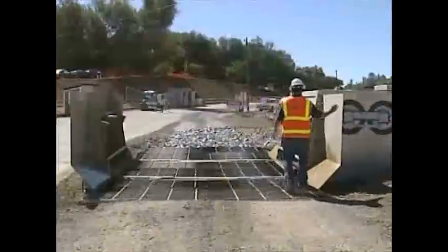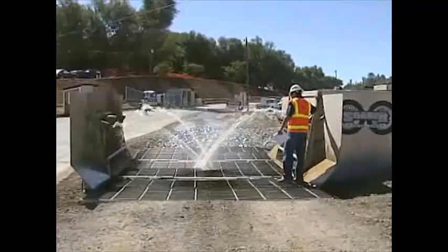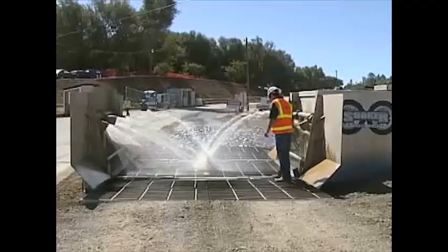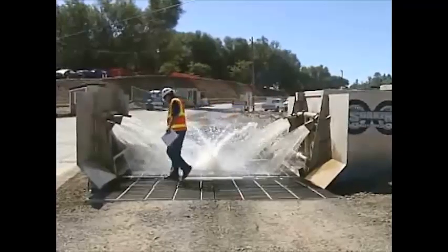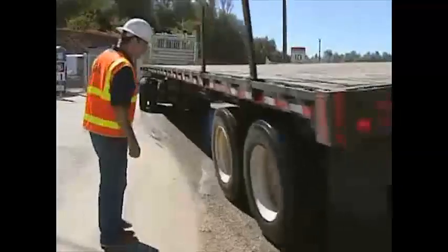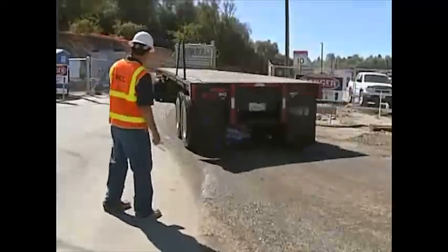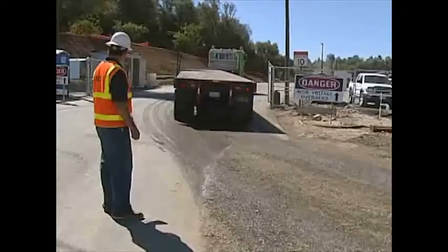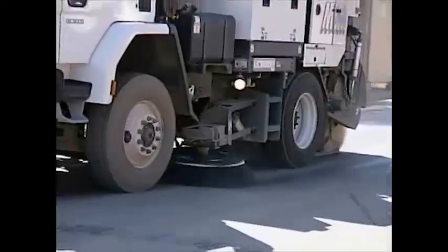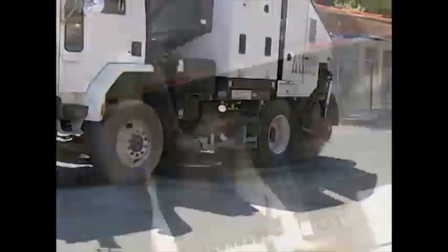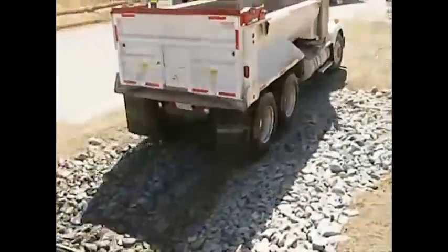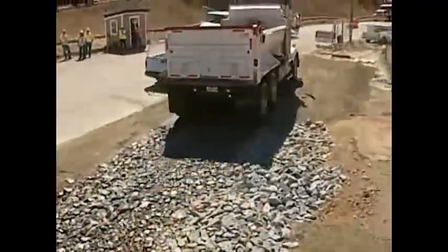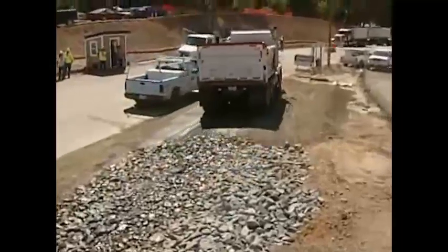Check for proper function of the tire wash as well as any form of damage to its components. If damage is detected, repair it as necessary or as directed by the resident engineer. Check to ensure that there is no tracking of mud or aggregate onto the paved roadway and that sweeping is being performed at an appropriate frequency. Check to determine whether soil and sediment or other materials tracked onto existing pavement are entering drainage facilities. Implement the appropriate BMPs if necessary.